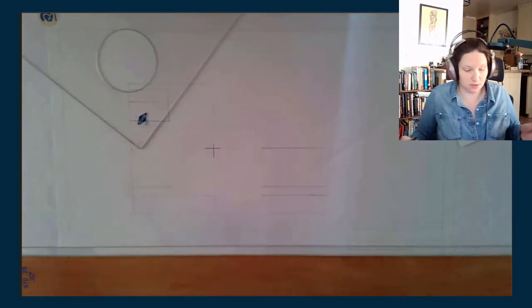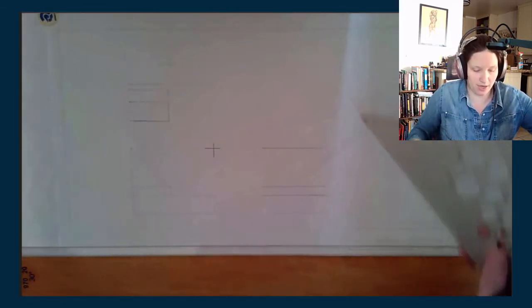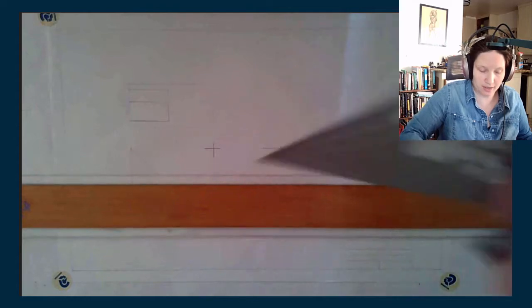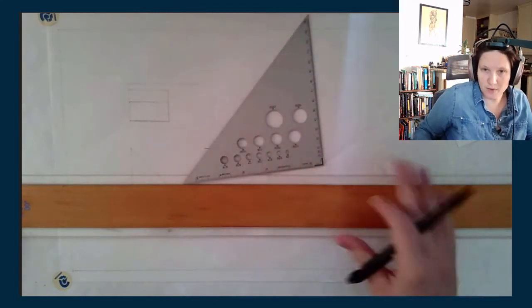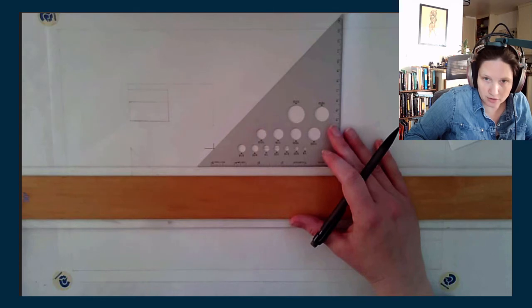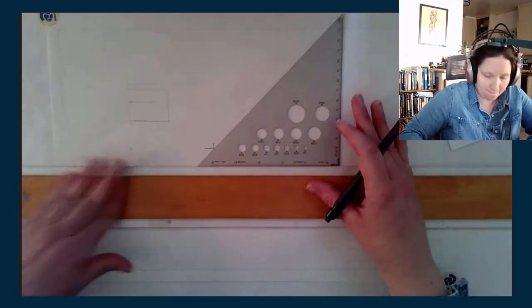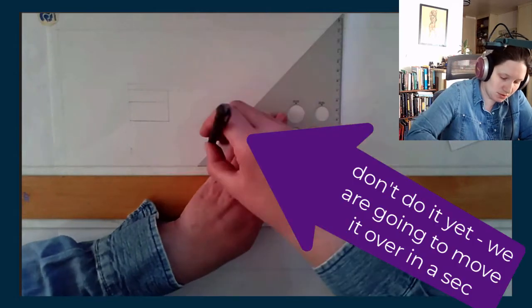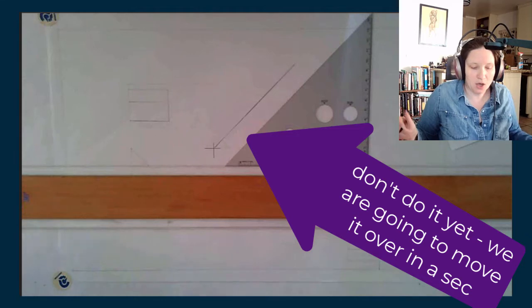All of the horizontals. Now let's get those verticals. The way we'll do it is across this miter edge. So I'm going to take my triangle, take a 45-degree angle. You can also do it this way, right? And line it up to that little cross that I made around the box, right? Then I'm going to draw this diagonal line. So there it is, diagonal line.